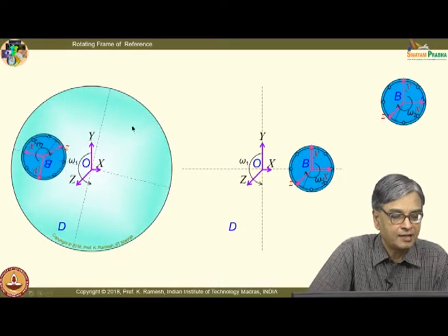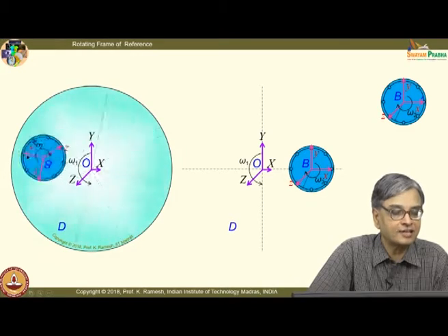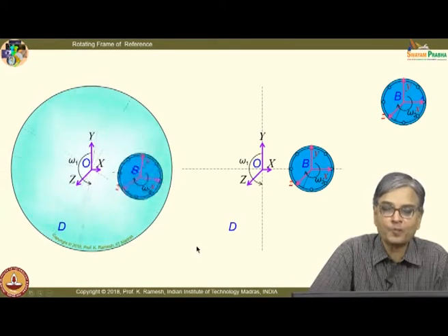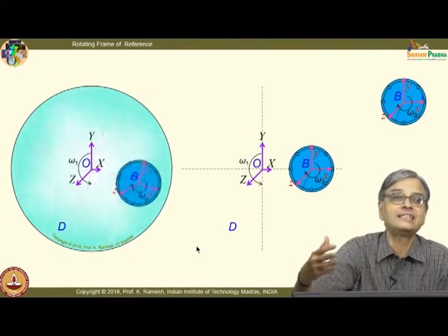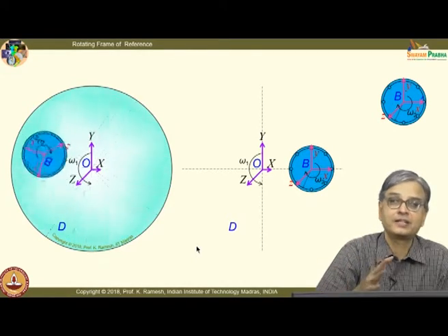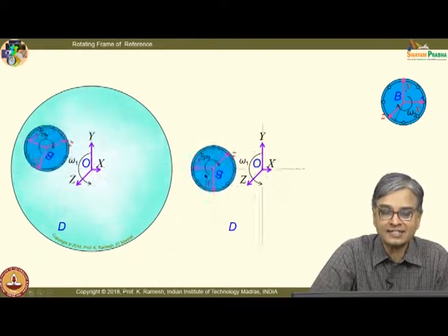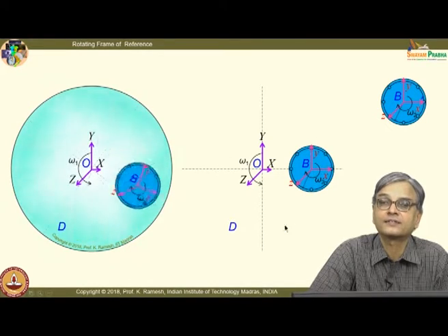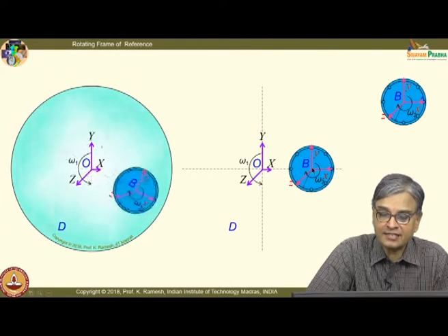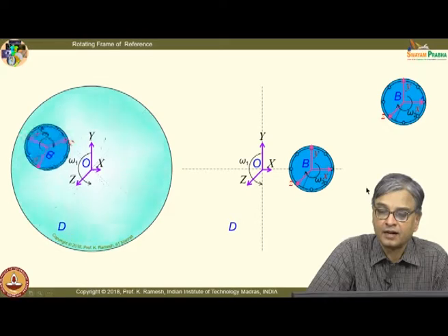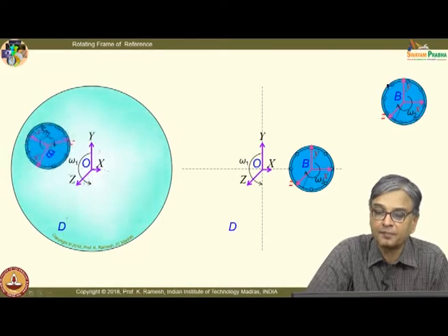So, I had a problem like this. I had the fixed axis attached to this, and I had the rotating axis attached to this, and I deliberately gave the problem that the disk itself is rotating because the V rel is easier to compute from circular motion. But the students, what they had the confusion was, you have to recognize that this axis is rotating with angular velocity omega 1, this axis, fine. And once I stand on point B, I would perceive that this is rotating in a clockwise fashion. And look at, I have a point A marked, the point A is moving.